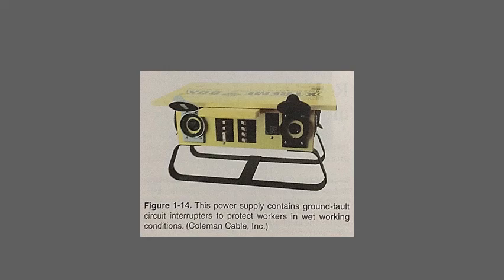Barricades and warning tapes are effective tools to alert others of hazardous areas. The main purpose of all these methods is to let others know about the environment they are working in. Another technique is holding morning meetings to alert crews of an unusual hazard, such as an overhead crane lift that is scheduled for that day. Communication among all involved is the most effective tool against accidents.